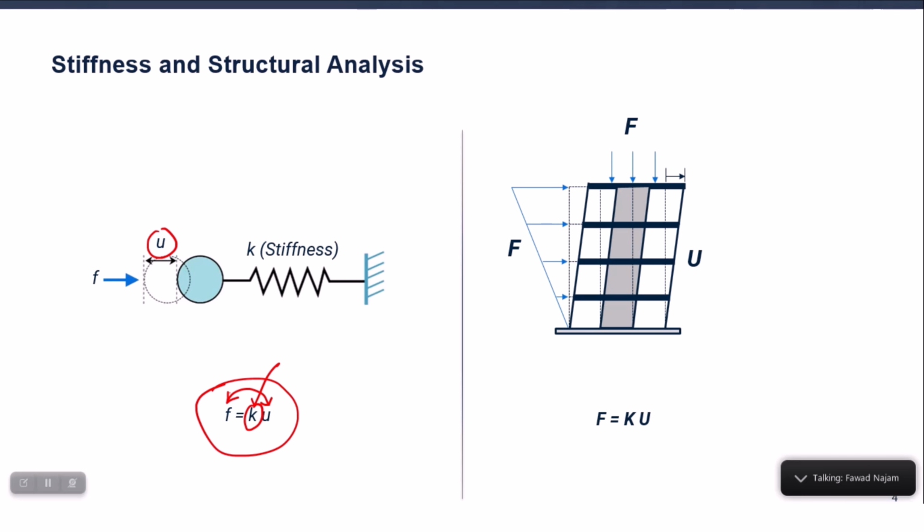So, the K quantity is a constant which is the stiffness of the spring, and it relates the force with the resulting deformation. We actually perform the same thing in finite element analysis at a very large scale. We think of our structure as a very complex spring, but it has stiffness in all directions, actually in all 6 degrees of freedom if you talk about all 3 dimensions.